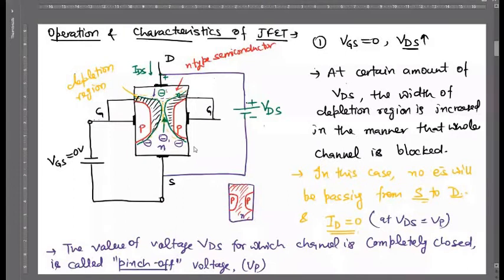Is it done in a piece of metal, or are different types of semiconductors joined here? Similar process, whatever I have already explained during the discussion related to diode, that we use the diffusion process for making the junction, and there is no process like joining of two different types of semiconductor. Understood? We make the diffusions in a pure semiconductor. Fine. Yes. Understood? Any other?